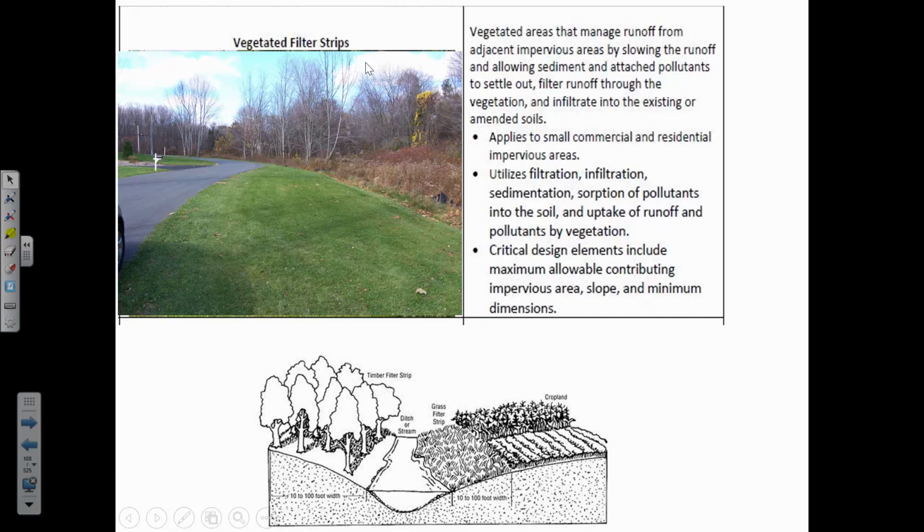An example, the new indoor practice facility that the football team has here on 3rd Avenue, they have a big series of cisterns underneath the parking lot to kind of absorb the first inch of rainfall and delay it and meter it into the storm drains at a slower rate than it naturally would get in there if there wasn't any kind of storage. Cookout is a newer business, and you may notice that Cookout has a porous pavement in their parking lot, and that helps to reduce the peak runoff that enters the roadway adjacent to it.